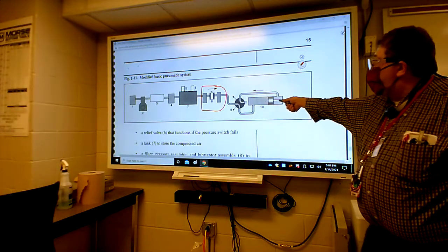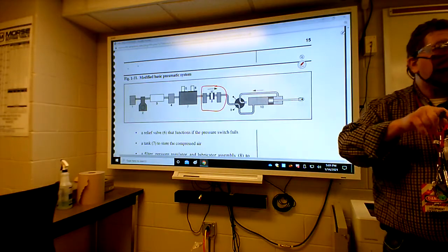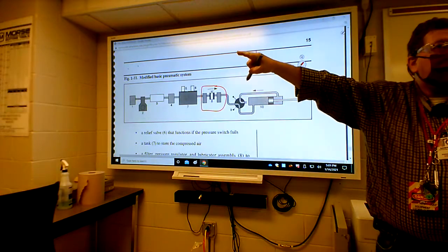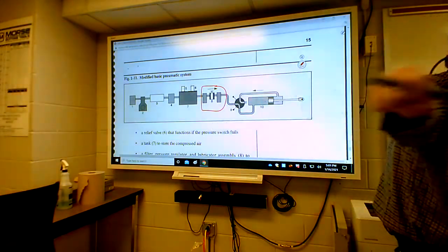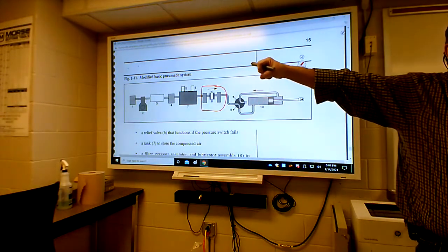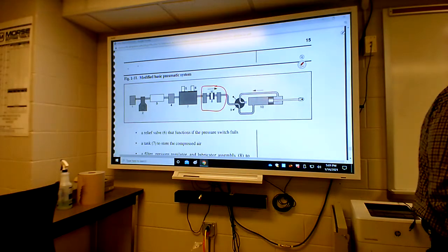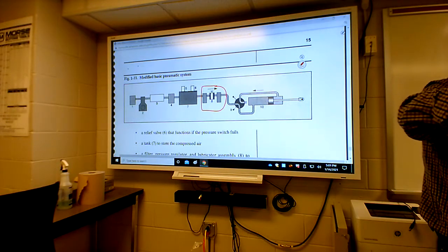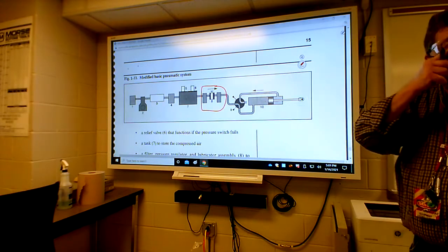Right, you have a cylinder here, and then sometimes you've got air motors. You've got rotary things that run, and sometimes there are rotary actuators that run in a swing arm. You remember how we looked back here in the automation system, and some of the things out there came around like this. It would grip, come around 180 degrees, and then go down and drop. That's a rotary actuator, that's air. So you've got the rotary stuff going on for pick and place, and you've got the air motors, and you've got even the grippers, and the vacuum tools, and a lot of stuff going on back there in that system that's air.